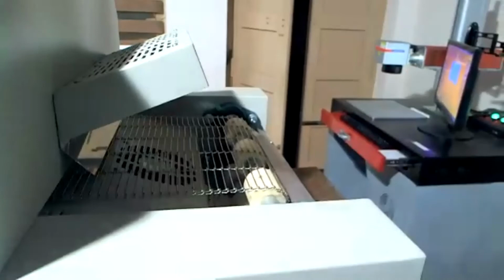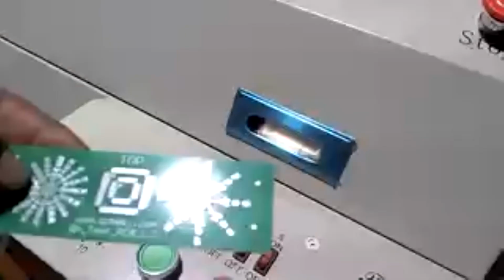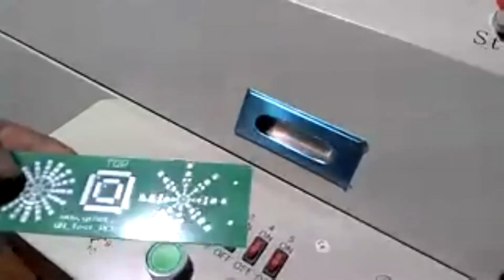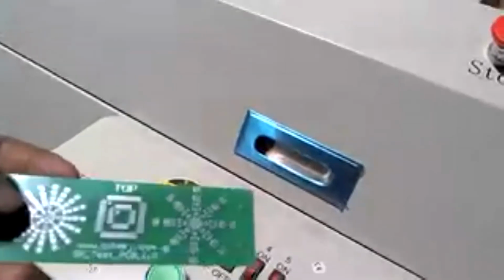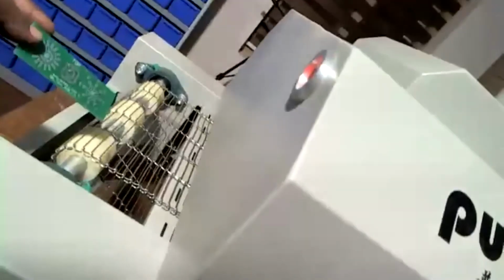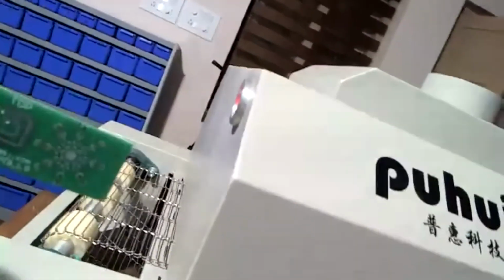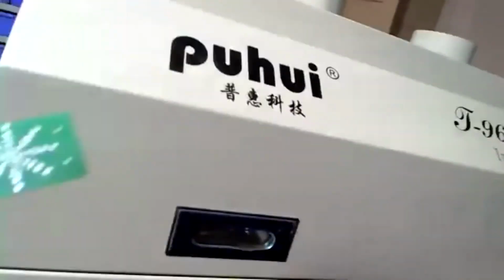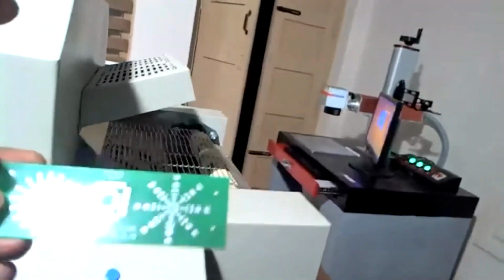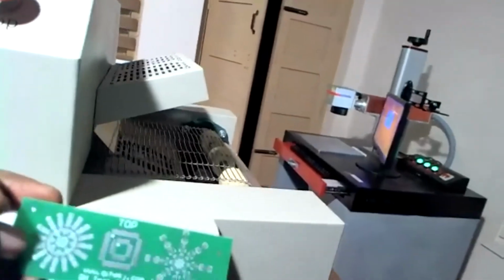It depends on what type of board you are using, what type of solder paste you are using, and what type of material is developed. Everything will be considered when you put it into the reflow oven. I kept it on this side, so it will come out on the other side. Anyhow, this is not required because no component is placed on this one. Once I get the outcome, my final board is ready, the product is ready. Even if you get the board made from outside, the placing, the reflow process and the stenciling need to be done by yourself. So this cannot be avoided.